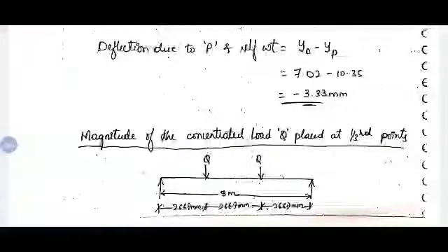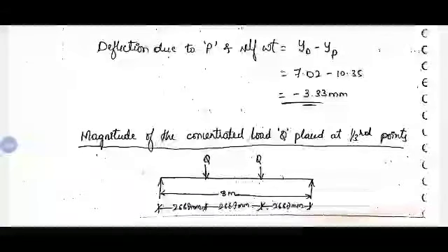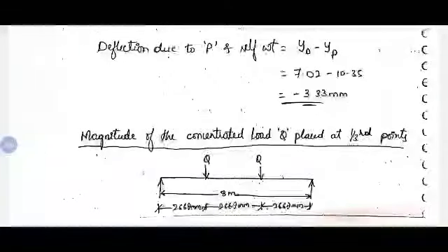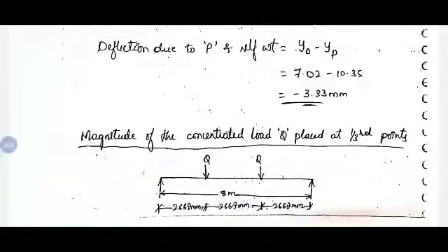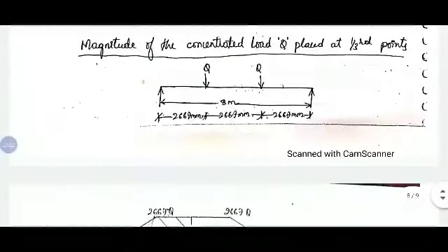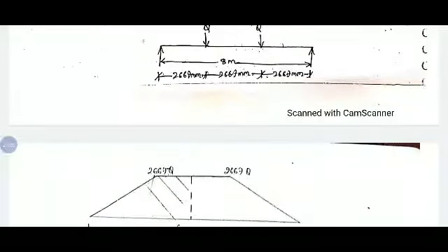Then in the third question, what you need to calculate is, live load is not given, but the condition is given that you are applying the live load at the third points. So when you divide the given beam into 3 equal parts, at the center 2 points you are going to apply the point loads, but we don't know what load is applied. That we need to find out. For that, the condition is given, span by 500 should be the allowable deflection. So span is 8000 divided by 500, how much you will get? 40 mm will be the allowable deflection.